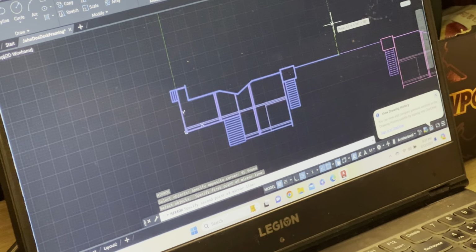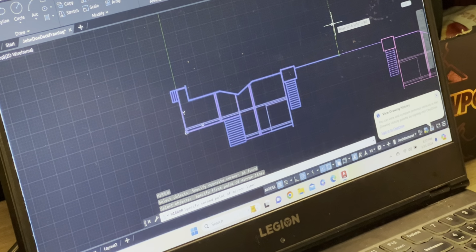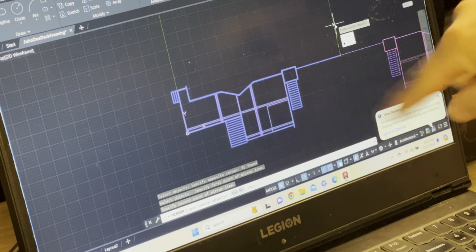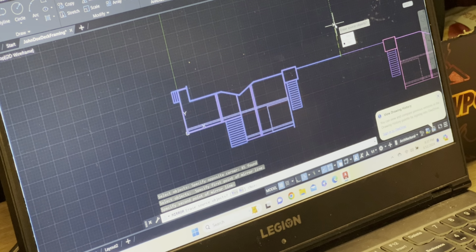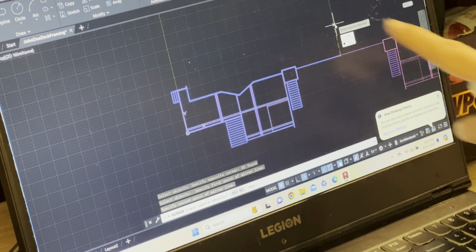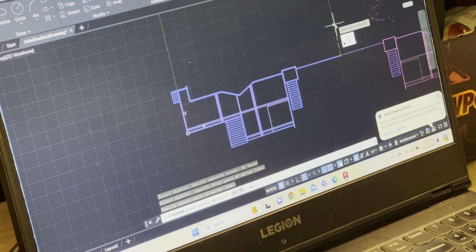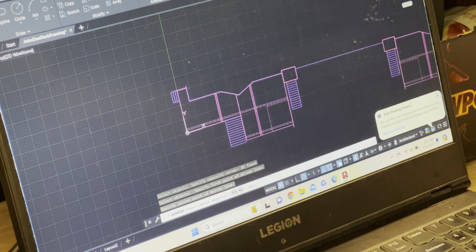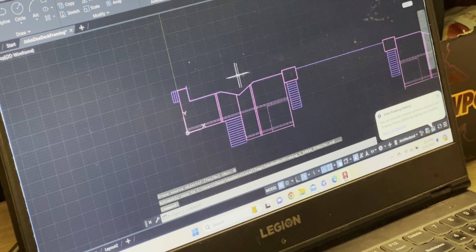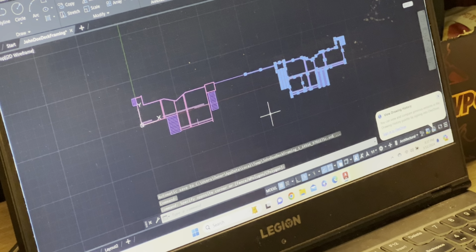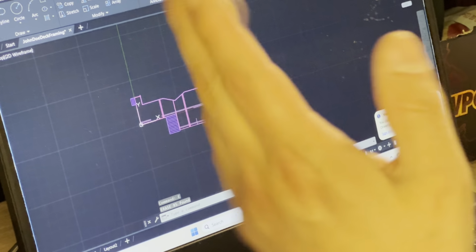But a lot of times what I do is it's just a matter of flip-flopping. So I'll click one point and then another vertical point straight from there, using my snaps, right? My grid snap or my object snaps. And then I'll go straight up from that and it'll just mirror it, flip-flop it straight over. And then it gives you an option. Do you want to erase your source objects? Yes or no? I'll click no. So it just gave me a mirror image. You see that? Sometimes that's important. For now, I don't need the mirror image, so I'm just getting rid of it.